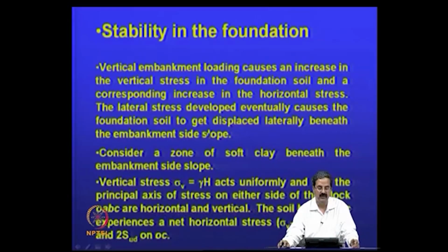But then you should go further. Then what is that that I was mentioning about the foundation extrusion, right? See, vertical stress causes a vertical stress in the foundation soil and a corresponding increase in the horizontal stress. The lateral stress developed eventually causes the foundation soil to get displaced laterally beneath the embankment side slope.